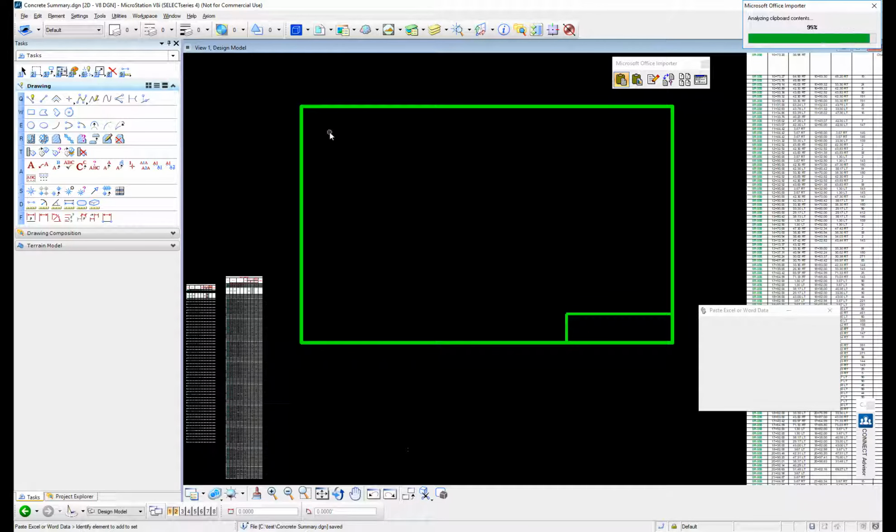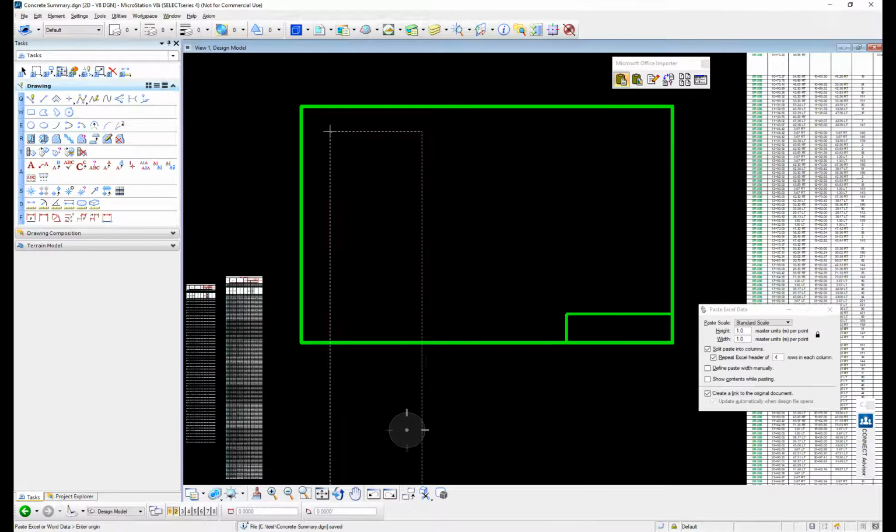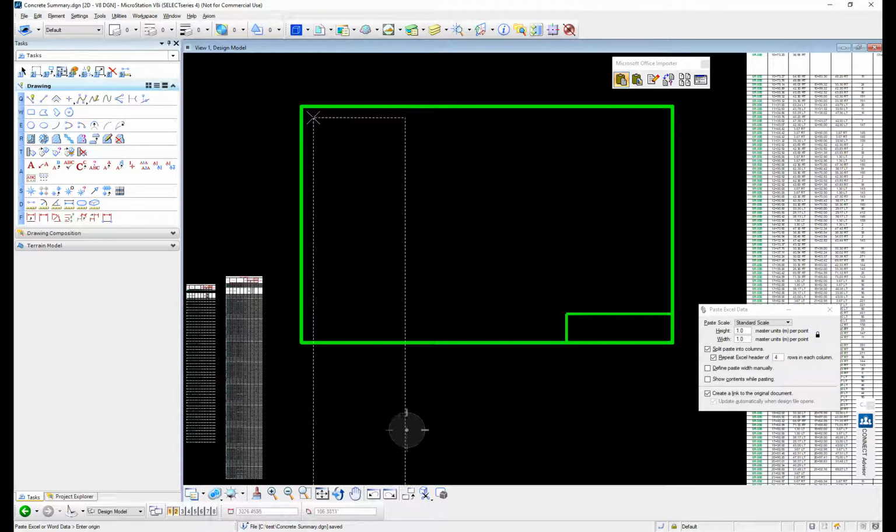And what we're going to do is immediately show you how much space that's going to take up. You can already predefine text sizes and scales and mapping, that kind of stuff. So this is already set up the way I want it to be for this particular project. By the way, you can even set that in your config files, your text sizes and stuff. So it can be in your MicroStation workspace. It can come from your managed workspace, whatever you want. So you come in here, you hit the corner, which is what I'm going to do. I'm going to hit the corner.